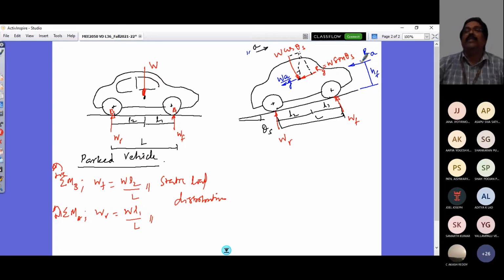Projected area of the vehicle means you look at your vehicle from the rear and project it on a wall with an orthographic projection. You get a rectangle accommodating the width of the vehicle and the height of the vehicle, and then you would get the CG location. That's where this aerodynamic force would act. And you also have in every vehicle a towing purpose.